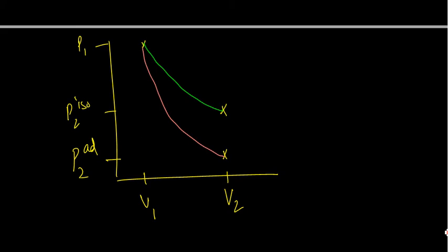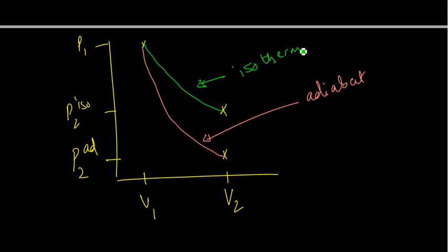Okay, so we are over here. This is my reversible case, right? So that's my adiabat, and again that's my isotherm. And remember, I can only draw the adiabat when it's a reversible case. I can only draw the isotherm when it's a reversible case, not otherwise. Otherwise, it's only the initial and final points. I don't know what's happening in between.